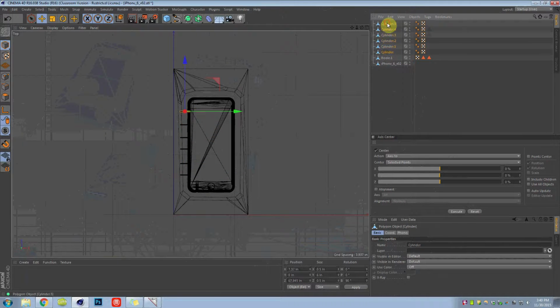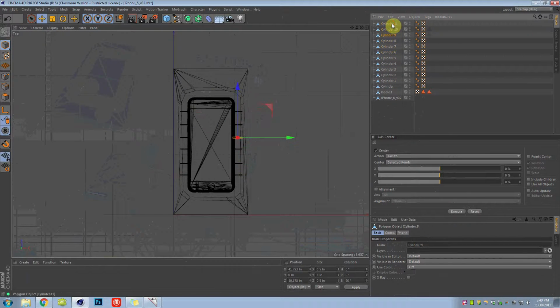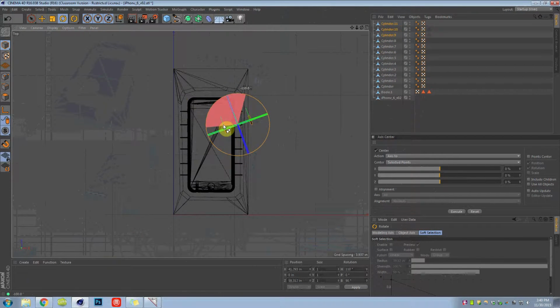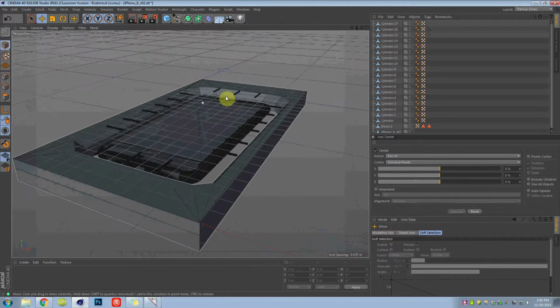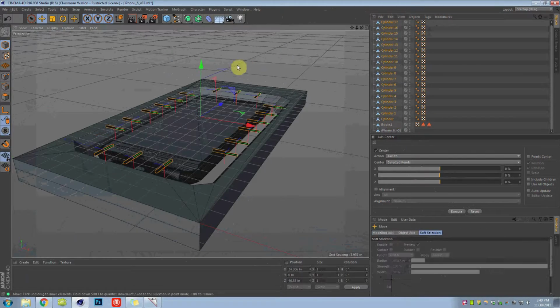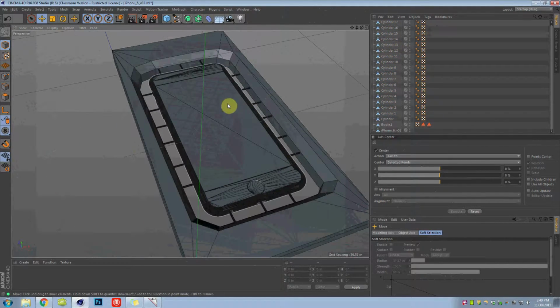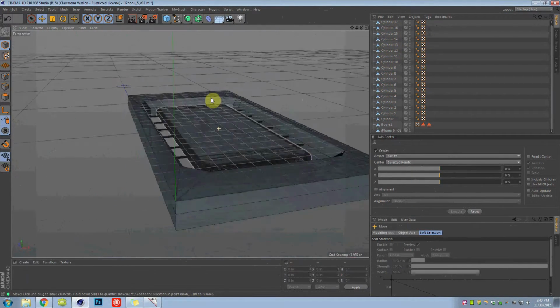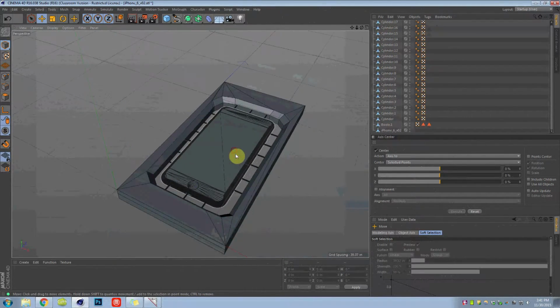This is probably way more than necessary in terms of connections, but I've found better safe than sorry in terms of milling. Now the beautiful part about the CNC mill is that you don't have to have a watertight model. Your models get read as a surface. So those connecting structures don't have to be booled together. They can just overlap like that.